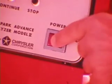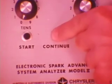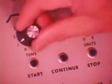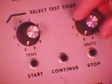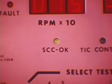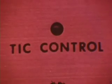There's a power switch, and start, continue, and stop switches, which you'll be instructed to operate at specified times. You'll program the analyzer with the select test code knobs to match the computer you have on the car. When the SCC OK indicator light comes on, that's the end of the test, and you know that the spark control computer is OK. The TIC control light is not used.